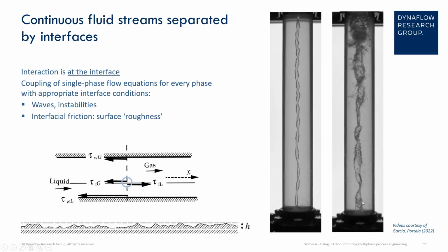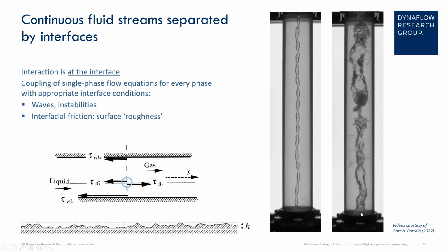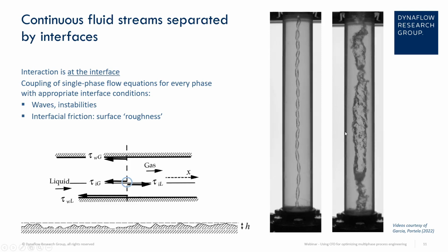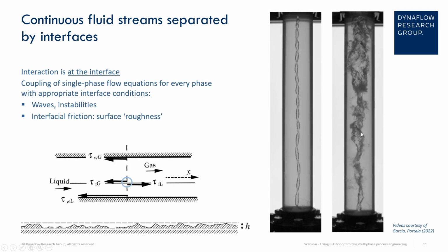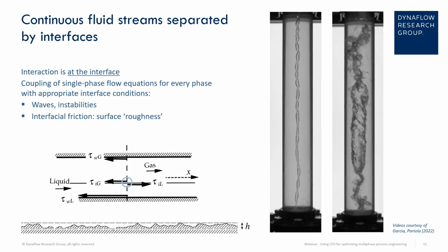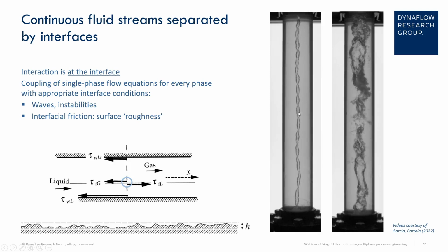But if you have higher gas concentrations, then the velocity difference between the bulk of the gas flow and the liquid revolving around it can be quite big. What you basically see is some kind of bursting of this central column into discrete droplets, and then these bubbles colliding once again to form a steady column. But this is much more unstable.